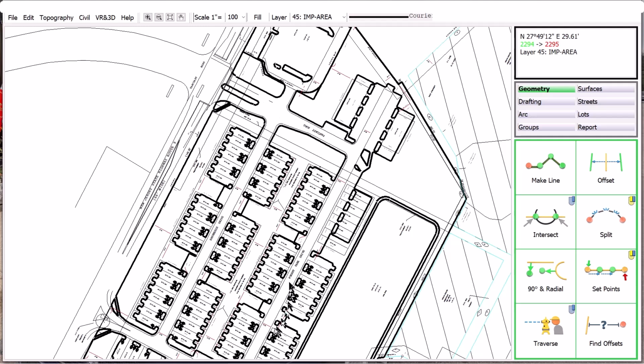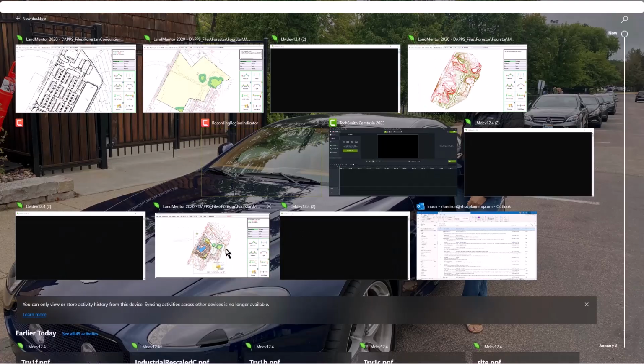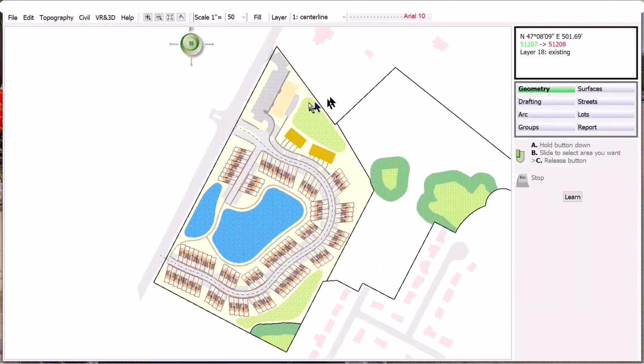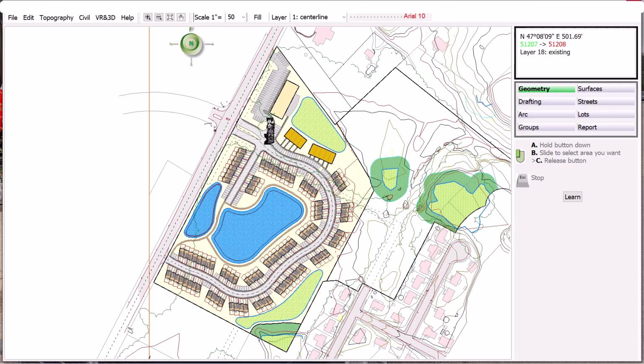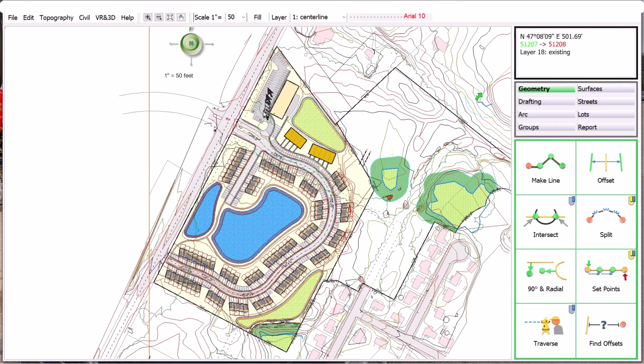So I'm trying to use every linear foot of pavement as possible, so overall the pavement area should be considerably less with the plan that we came up with. So let's show you what we did. And again, you could see the commercial area, we're coming in about the same, increasing the parking spaces. I think I've got pretty much double, if not more, parking spaces. So we're able to increase the square footage of the commercial. I don't have loading docks in the back. I have social area. And I put the bioretention ponds by the wetlands.